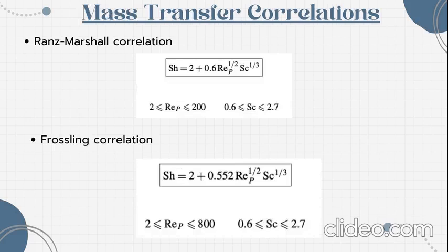Next, we will discuss mass transfer around a sphere. Mass transfer also works similarly. When a sphere is immersed in an infinite stagnant fluid, the analytical solution for the steady state diffusion is possible, and the result is expressed in the form Sherwood number is equal to 2. Now in this case, the fluid motion, the contribution of convection must also be taken into consideration.